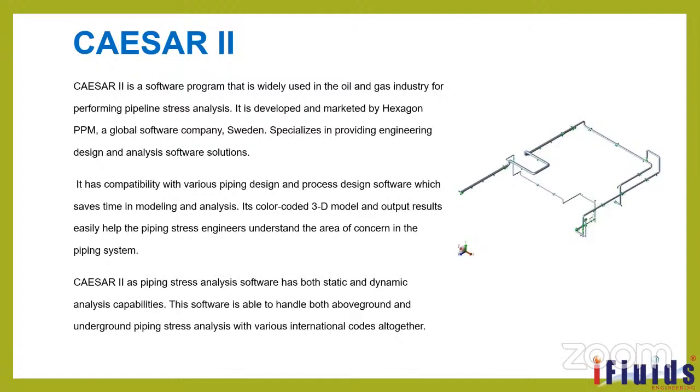It has compatibility with various piping design and process design software, which saves time in modeling and analysis. If I want to do any stress analysis that is complicated to do in Caesar 2, we make the model in Plant 3D and then export it from Plant 3D to Caesar 2 to analyze the pipeline stress. And also from E3D we can import the 3D model into Caesar 2. So it can help the piping stress engineers understand the area of concern in the piping system.